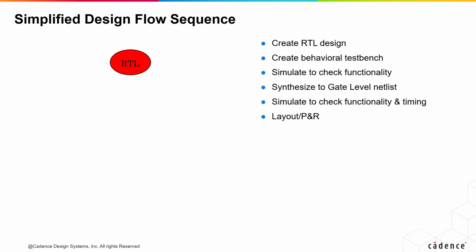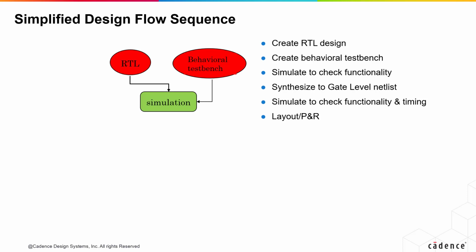Typically, a design is entered directly in RTL VHDL. The RTL must be functionally verified using a VHDL simulator. A test bench model is written to apply stimulus, extract results and verify results. Since the test bench will not be synthesized, there is no restriction in the use of language constructs or modeling style. Hence, they are written in behavioral level VHDL.